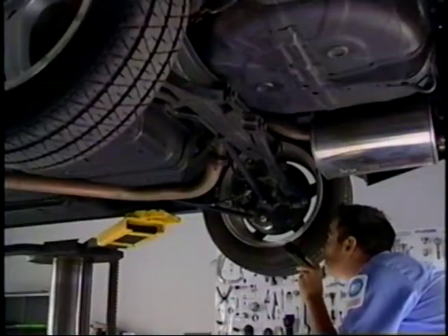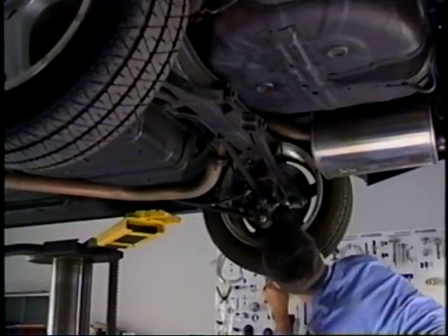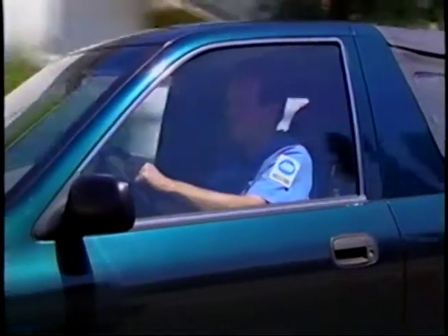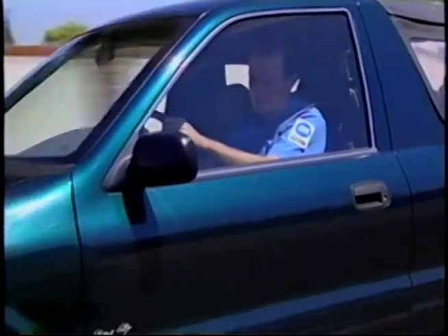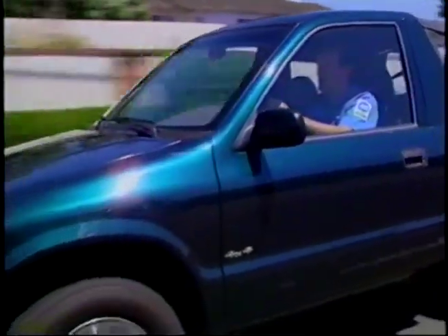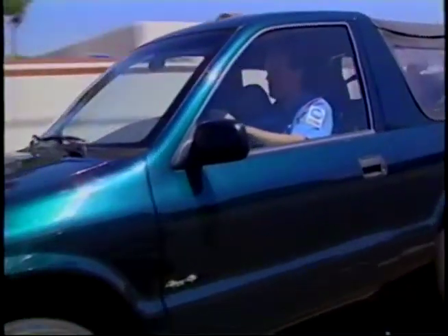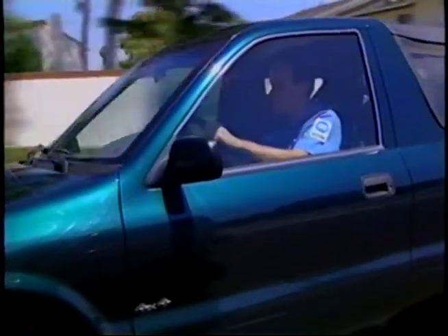When diagnosing noises, excessive body roll or ride height concerns, look for wear on the rear suspension components. When troubleshooting problems with any of the suspension systems, keep in mind which systems cause vibrations, which cause noise, or which cause poor handling, and isolate the cause of the problem from there.